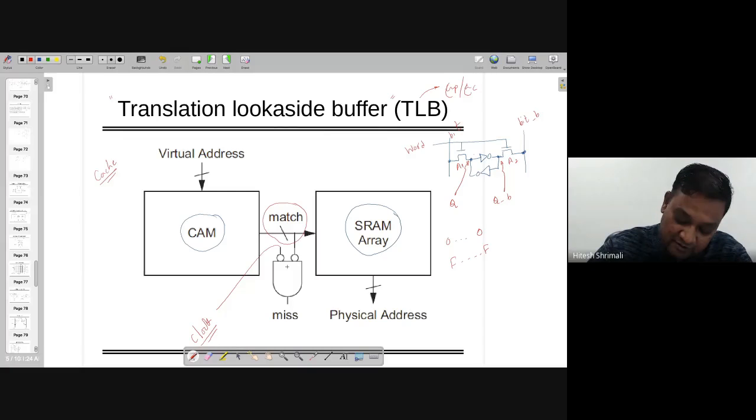right? So on the clock, if match data are equal to 1, this is what we want: all the match data, as this is multiple lines, so it's a bus of different lines. In that case, all of them are 1, then this is acting as 0 and miss equal to 0. When clock equal to 0, if you want to read the data at clock equal to 1, simply you can remove this one and have the logic 1, right?